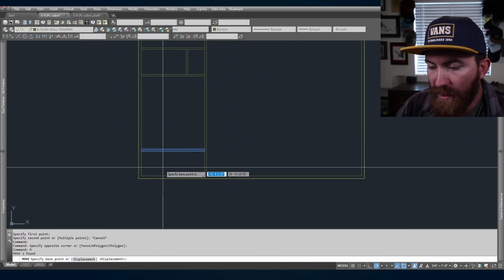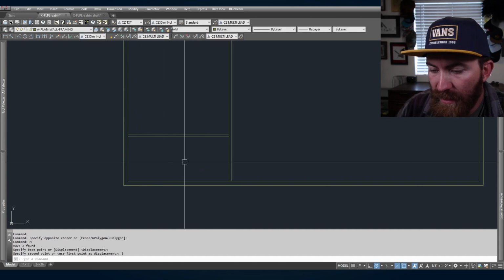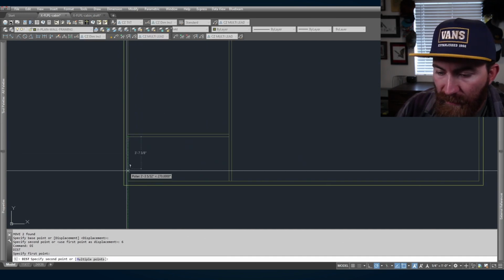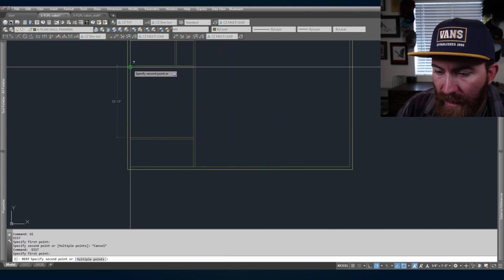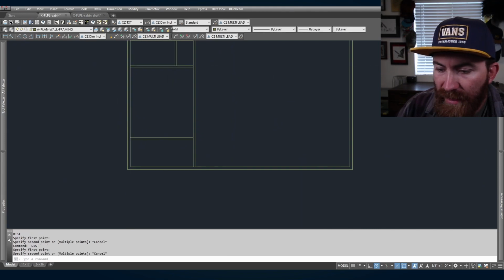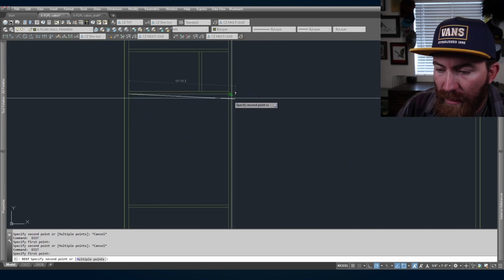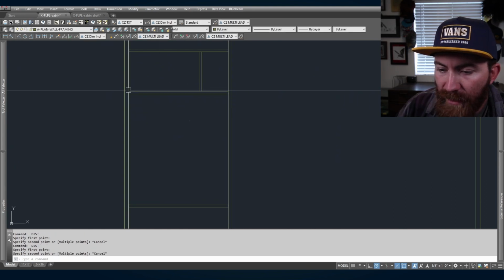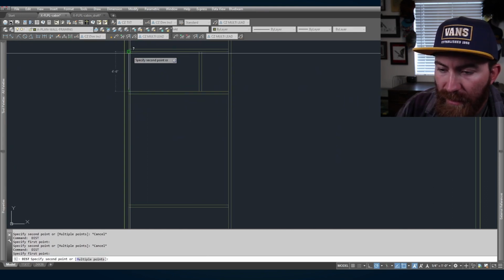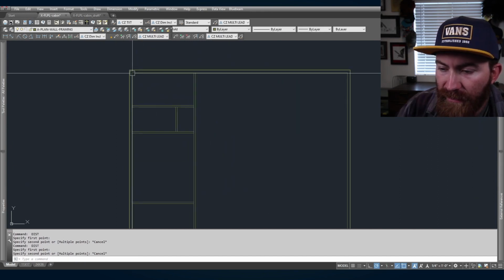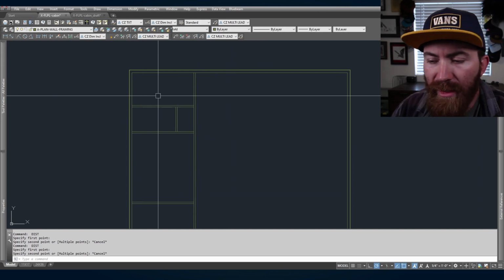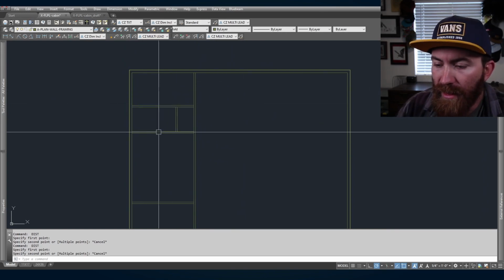So what I'm gonna do is I'm gonna make this mudroom just a little deeper, 6 inches. So now we've got essentially 5 foot clear. We've got 12 foot 7.5 in the bedroom by almost 11 foot, over 11 foot. This is a little closet that's 4'6" wide, and this is the bathroom that is 6 foot wide. And we'll go into probably another video on laying these out and laying out the kitchen.